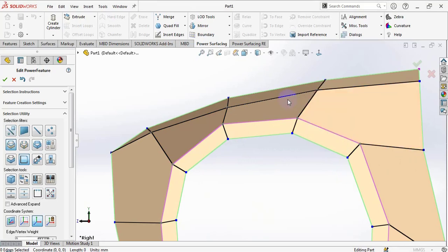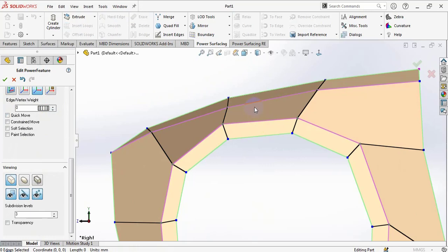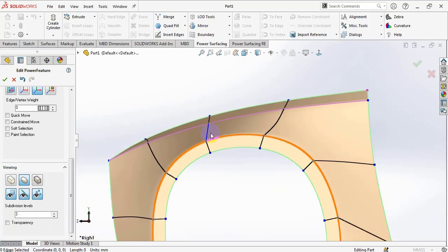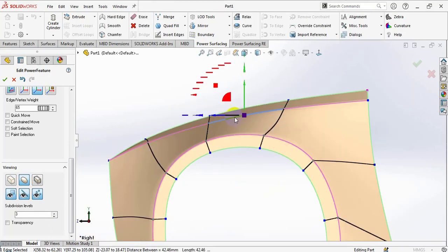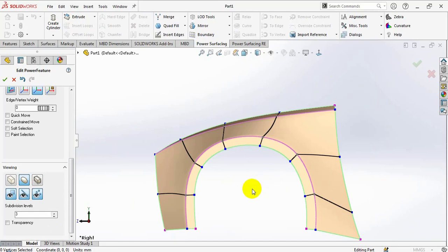Okay, just selecting this ring loop, make it 64 and press the arrow to apply it. Now I'm just selecting the display subdivision surface. As you see, it's gonna be like this. Just up this a little bit, like this, and here too.